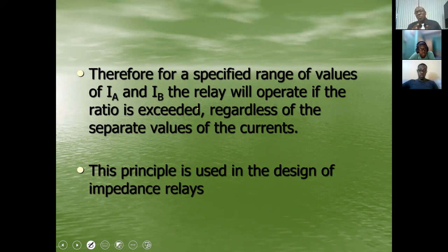For the derived quantities, once we are going to be looking at power or impedance, it means that we are going to be using a VT and a CT. And what we said last week, because of the expense and the size for your VTs, ideally we use only one VT. So we don't replicate VTs unless, of course, the utility is awash with money and they really want full redundancy. But you hardly ever replicate VTs.